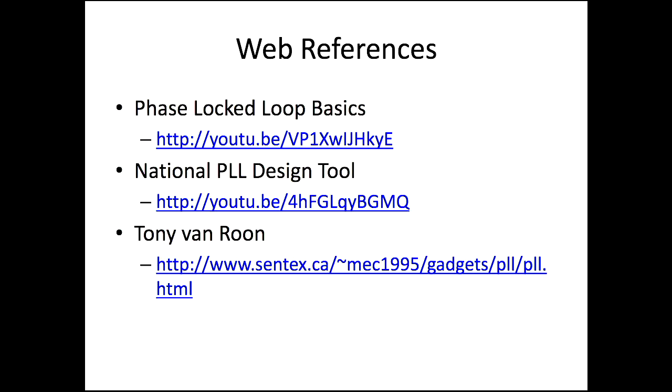And now my next lecture I will start power supply design, because power supply design is important again for a system engineer. You should know how the power supply works. Most of the time you will be buying a power supply like a regulator, but we should know the power supply. If you don't know about the power supply, we can make several mistakes like noise filtering. For example, you are using a linear regulator, series regulator, parallel regulator, switched mode regulator. You can buy off the shelf ICs, but then we should know what are the differences. How it is working, how voltage is stepping down, how voltage is stepping up.